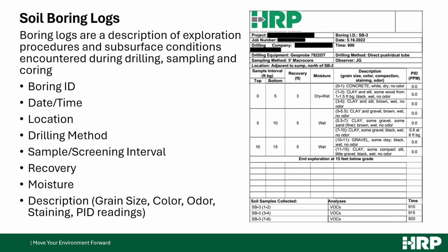So this is an example of a soil boring log. This was collected by John Gorman. Basically, the boring log helps us organize our thoughts and observations when we collect a soil sample, usually using a geoprobe with direct push. And what's important when developing these soil borings is to write down what you're seeing. Especially when you're starting this site investigation, you won't know what the important information is going to be.